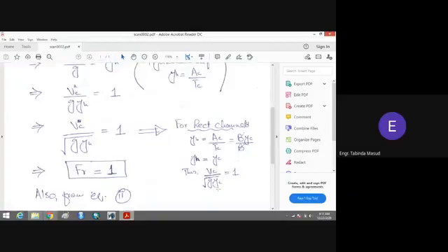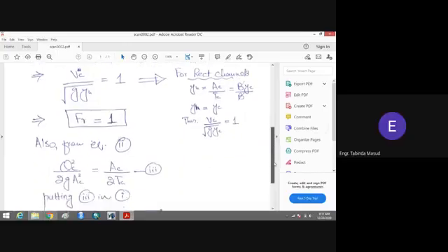That equation you can use only for the rectangular channels, remember, and for all other types of channels you can use the generalized equation. Students often make a mistake here. We ask them to find the Froude number for the triangular or any other kind of channel, and they mistakenly use the rectangular equation, which gives a wrong answer. So be careful about using the equation and make these concepts clear.